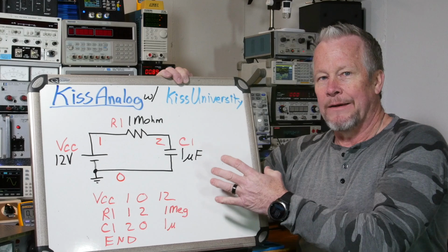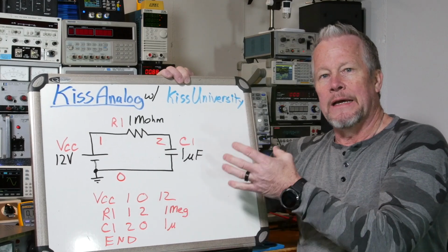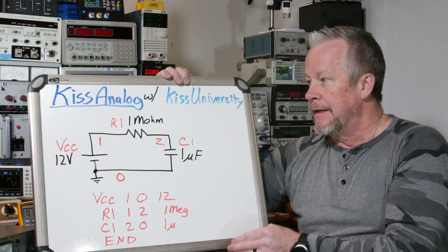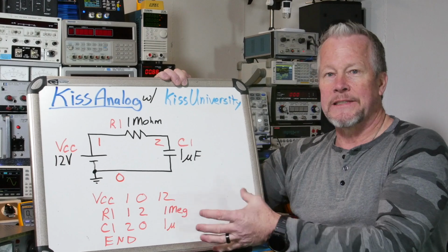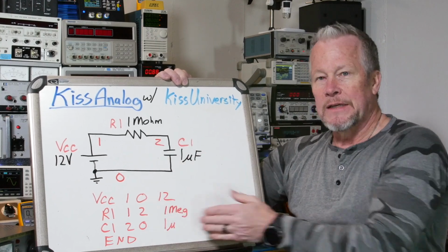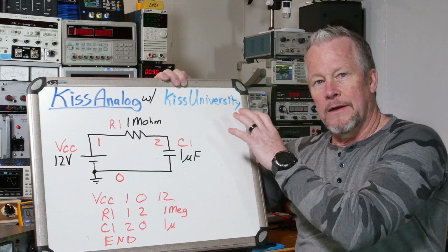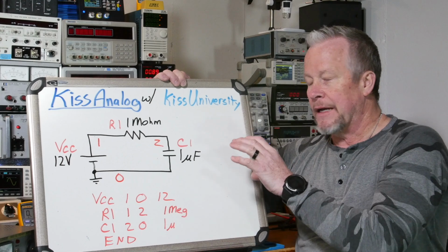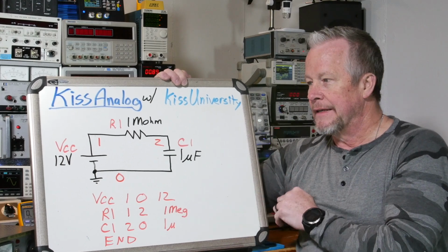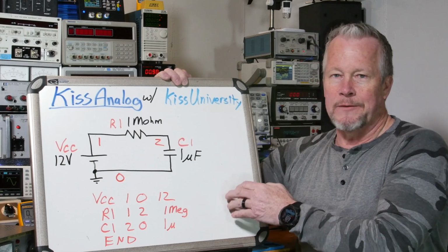So that's kind of the introduction of where SPICE came from and how the circuits are built, and why MicroCap and Intusoft and SPICE programs like that make Berkeley SPICE a lot more usable and easier to use, because you don't have to do this. Now on Berkeley's website, they do have the latest SPICE, but they also have an interface. It's been years since I've tried to use that interface, but it's not going to be like MicroCap.